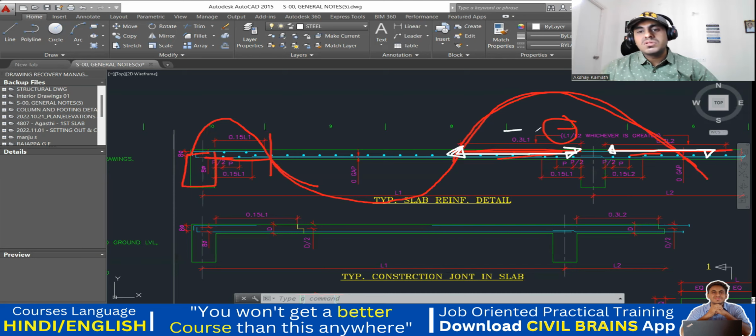So that is why we are giving 0.3 and 0.3. Whereas here, this negative bending moment impact is on a lower side, and that effect will be seen up to this length only. After that, this negative will turn into a positive, and then it will come into sagging. Only up to this. So this portion is 0.15.